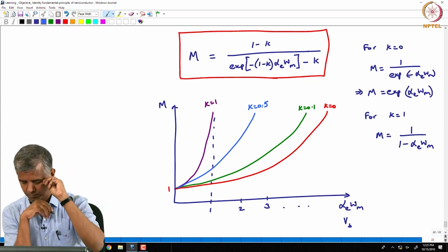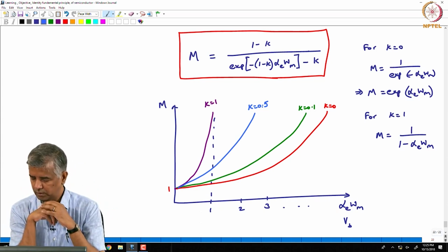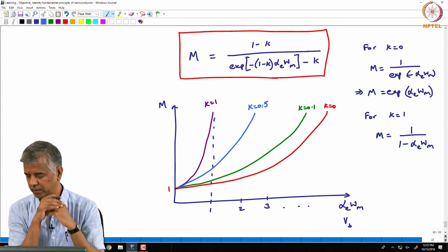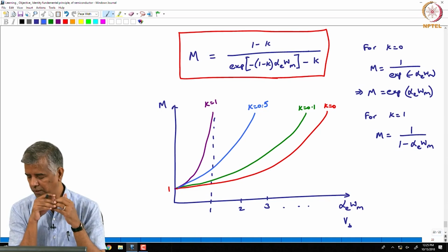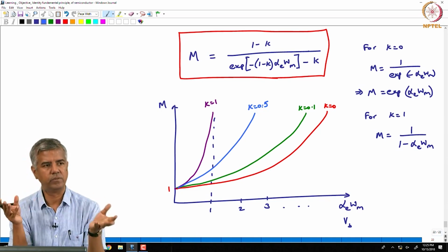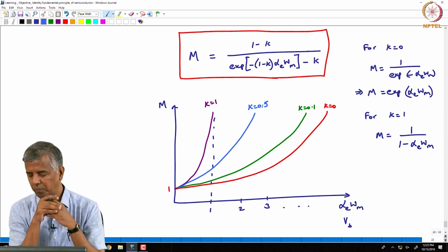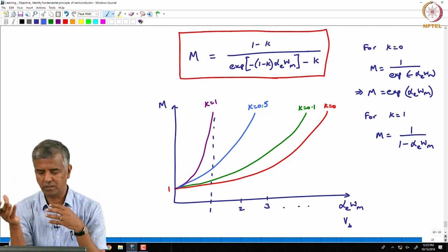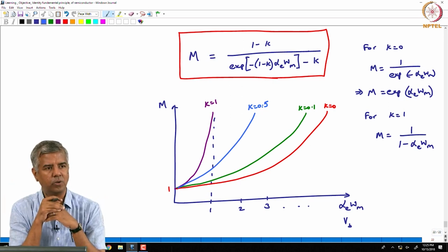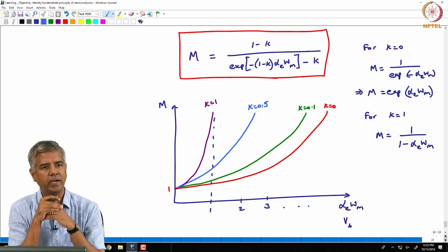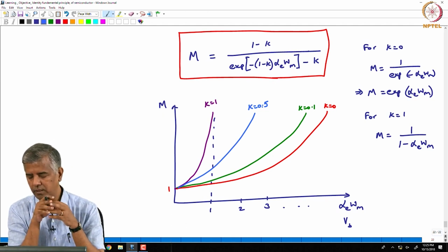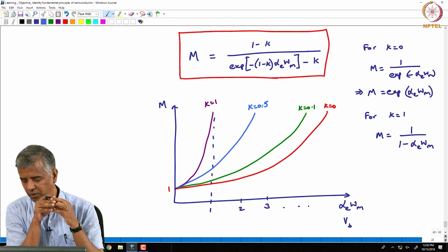So, yes, indium gallium arsenide you can say has got higher impact ionization coefficient. So, even for low voltages it gives you much gain, but beyond a certain point you start triggering your holes also to provide the avalanche multiplication. So, that can become very noisy.